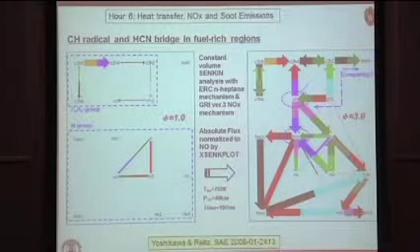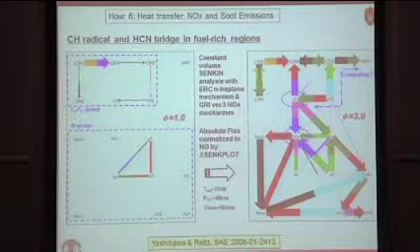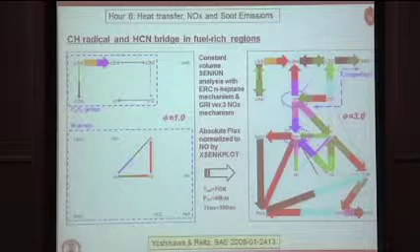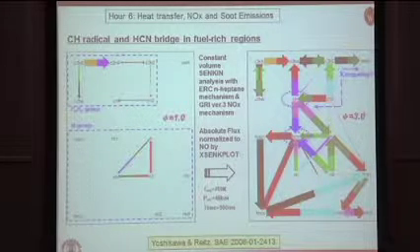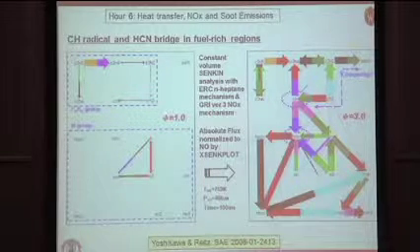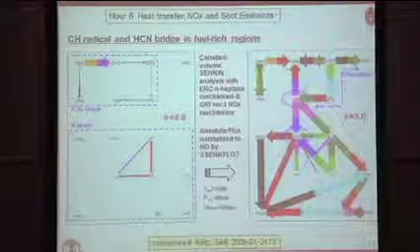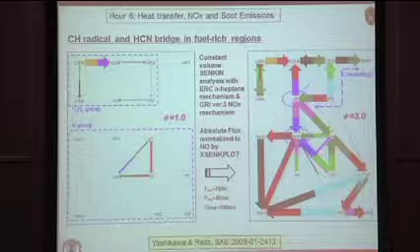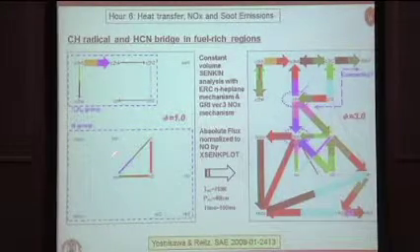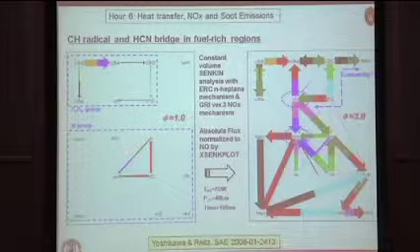Another interesting thing that one of my students, Takeshi, explored a little bit was the connection between NOx and soot. From a kinetic standpoint, it was kind of interesting. If you look at lean mixtures or even up to stoichiometric mixtures, there's not a very tight connection between the species that are associated with soot production, which we'll be discussing in a minute, such as acetylene, and the species that are involved in NO production.